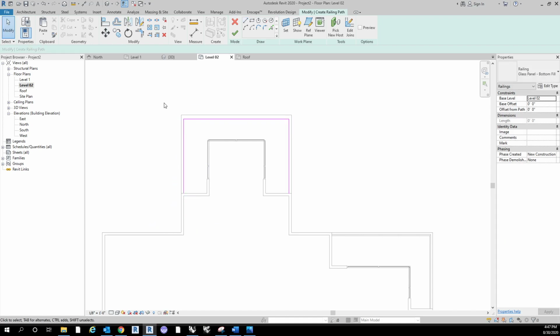Here, actually, let's show you the offset tool. So, like walls, like when we were creating our floor boundary, you can use any of these drawing tools up at the top. And what we can do is use the pick lines to select the outside boundary of the floor slab. Click and drag these up so that they're in line with the wall. And then we can use the offset tool under modify to offset the lines in from the face of the slab, the 8 inches or so that we had before.